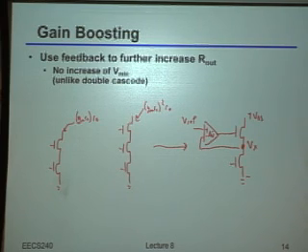By the way, if you remember when we looked at the original cascode, we said there was a Vx there, and we compared that to the swing on the VDS. What did we say was the relationship between the swing on Vx and the swing at VDS? How are those two related to each other? Yeah, it was reduced by the gm ro of the upper transistor.